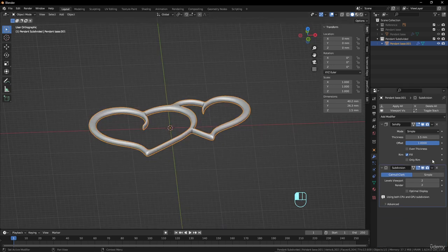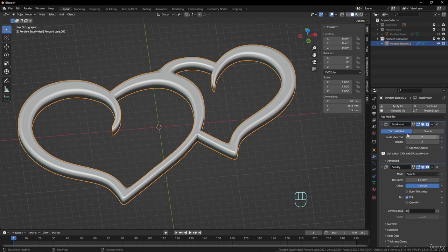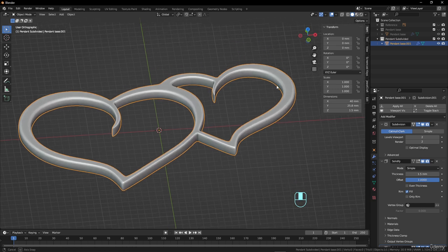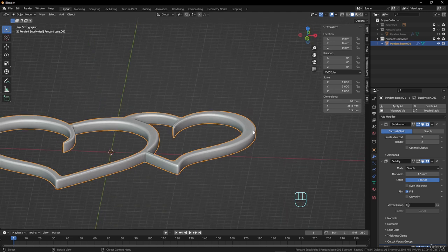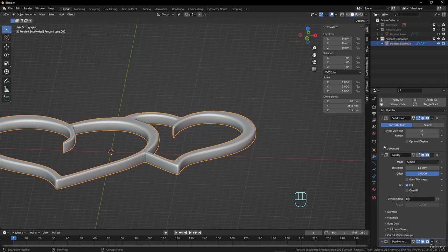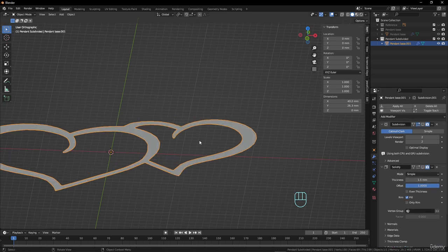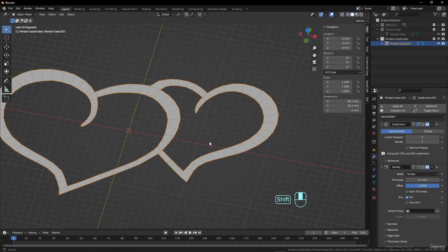But if you put the first one, what's happening here? You read the modifiers from the first to the last, actually. That's why they make different effects here. I will add the last subdivision surface here to show you that, to have the roundish version, square, but with smoother edges. So what's happening here? We come back to the beginning. I hide these modifiers in the beginning, and I will show you the geometry really made with that to understand what's happening.